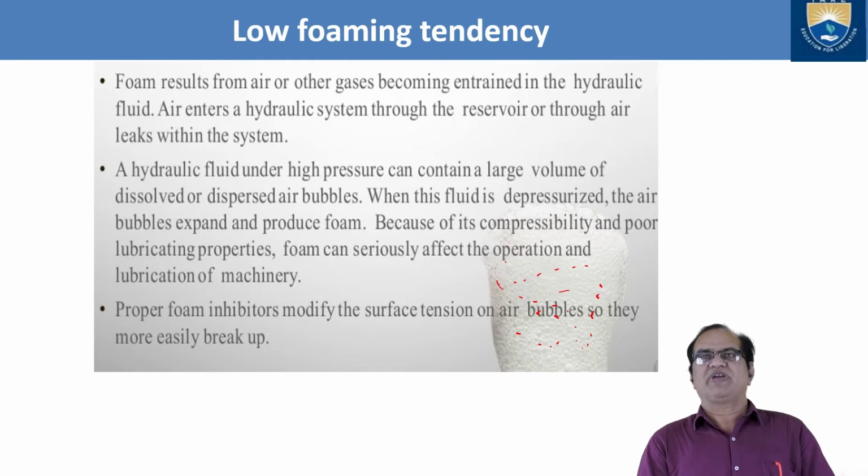So foam results from air or other gases becoming entrained in the hydraulic fluid. Air enters a hydraulic system through the reservoir or through air leaks within the system. A hydraulic fluid under high pressure can contain a large volume of dissolved or dispersed air bubbles. When this fluid is depressurized, the air bubble expands and produces foam. Because of its compressibility and poor lubricating properties, foam can seriously affect the operation and lubrication of machinery.